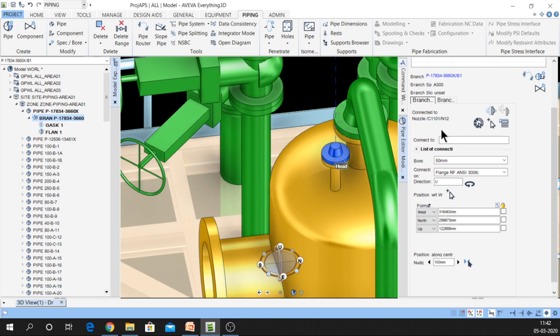Now we will do the piping step by step, and we will not connect the branch tail. We will just leave it as it is. Now we will go to the component creation form. See, create component. Once we click this, the component form will appear.